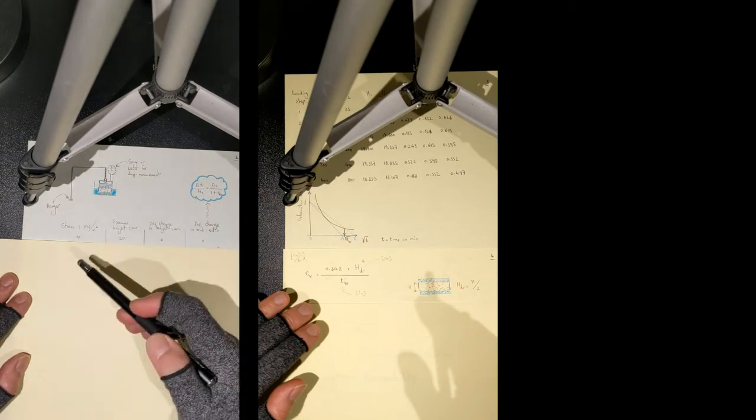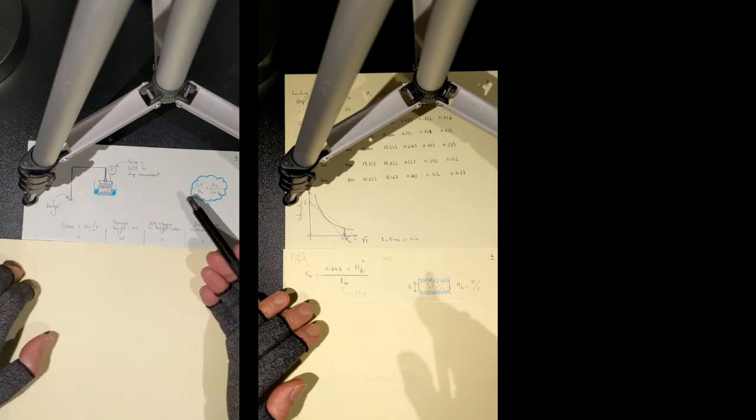Look at this golden equation. You probably may like to memorize this golden equation because you will use it on a daily basis as a design engineer. Delta H divided by H0 is equal to delta e divided by 1 plus e0. What is this equation telling me? Delta H is settlement or heave, volumetric change along the axial vertical axis. Basically it's the reading of this dial gauge, or the actual settlement in the field.